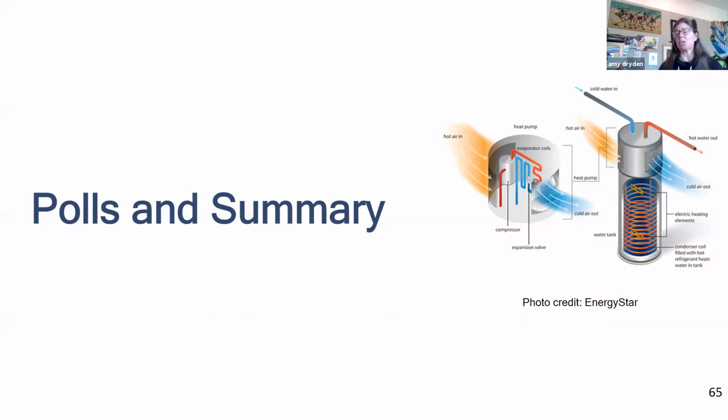Just from an efficiency standpoint, they're incredibly efficient. If we think about natural gas and your standard atmospheric water heater in the majority of California homes, those have an efficiency of like 0.57, 0.62, 0.67. That's super inefficient. Plus they're combustion appliances, and depending on where the location is, you can be subject to inefficiencies or ineffective venting.